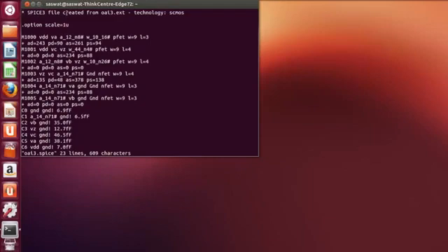Now see, it's written spice3 file created from OAI3.ext technology SCMOS. The scale is 1U. We have 1, 2, 3, 4, 5, 6 MOSFETs, 3 PMOS, 3 NMOS. You can see the first PMOS has different W by L ratio. Why? Because the width was 9 as same as the others and the length was 3. It was the shorter one. And these two PFETs are of width 9 and length 4. Why? If you remember, these are the PFETs where they were combined in one.